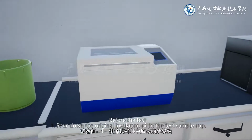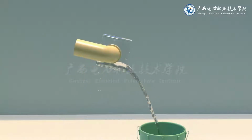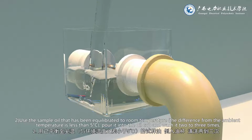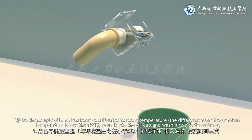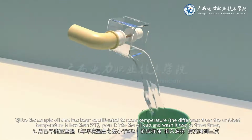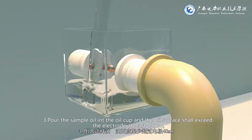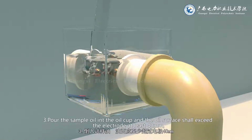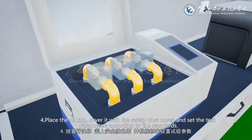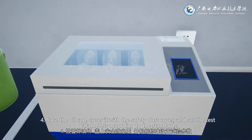Before the test: 1. Pour down the original insulation oil in the test sample cup. 2. Use the sample oil that has been equilibrated to room temperature. The difference from the ambient temperature is less than 5 degrees Celsius. Pour it into the oil cup and wash it 2 to 3 times. 3. Pour the sample oil into the oil cup and the oil surface shall exceed the electrode at least 40 mm. 4. Place the oil cup, cover it with the safety dust cover, and set the test parameters according to the standards.